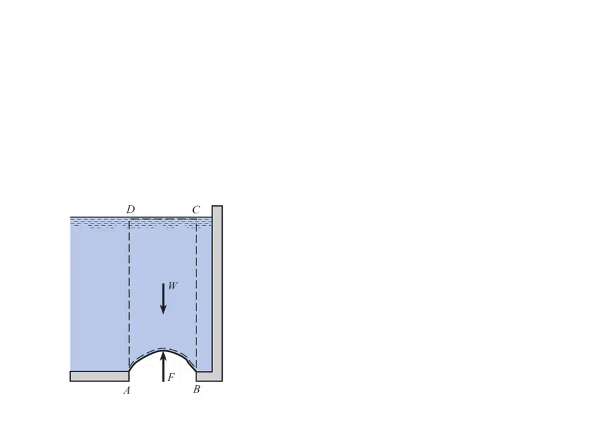Think about this scenario where we've got an irregularly shaped gate keeping water from coming out of an orifice. Now, the way that you'd find the force required to hold this plate steady would be the direct way. You'd find out what's the pressure at every point. You'd break it up into lots of little pieces, and you'd find out what's the pressure for this piece, what's the area of it. So the force is pressure times area. The numerical method is to integrate for lots of little elements.